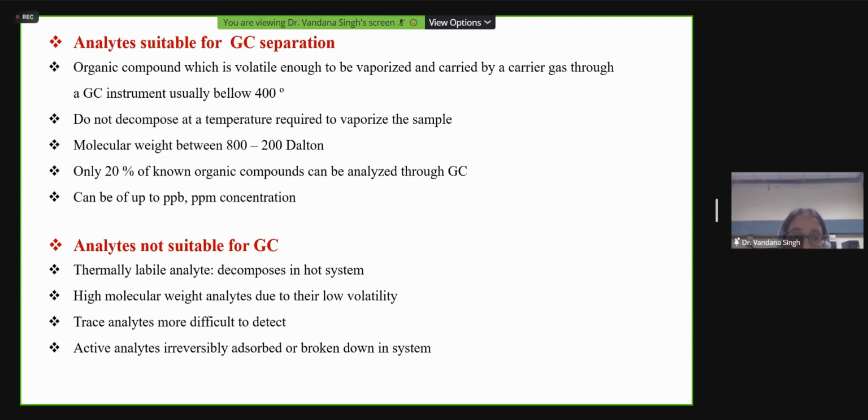This is all an automated process, where in these tubes we keep our samples, and this is the syringe loading compartment, where the micro syringes, which are generally quartz needles, are fitted, and they robotically, automatically plunge into the sample loading vials and take the required amount of sample. All of these settings are made in computer software, and according to that setting it operates.